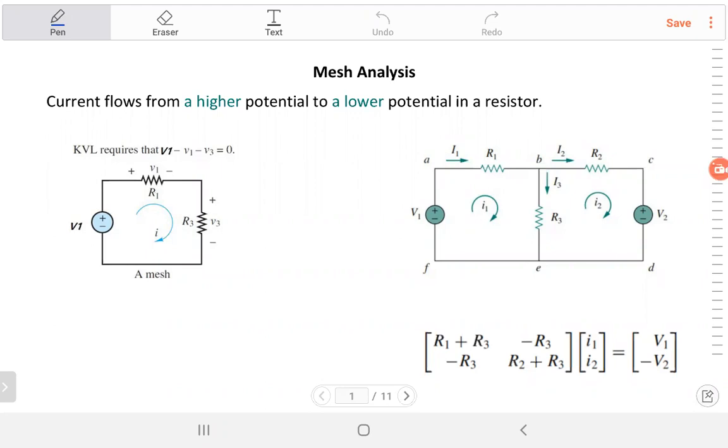Last lecture, we explained how to solve electric circuits with DC sources using nodal analysis. Briefly, it's used to find the voltage at each node. It uses Kirchhoff's current law. It's easier if you have current sources. And if it has a voltage source in series with a resistance, we can convert it to a current source and continue to solve it in a simple way using the matrix.